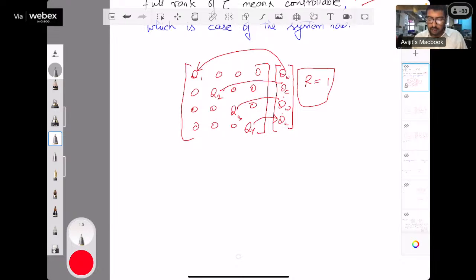So what does this represent? The higher the weight of the diagonal element of the corresponding Q matrix, the higher the restriction that will be put on that state.